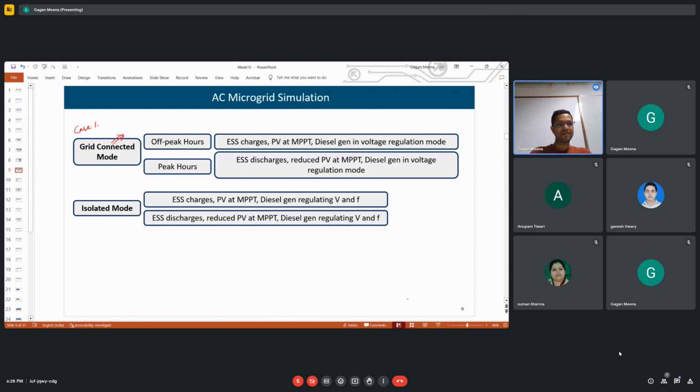So it will become L11, which is a self-inductance, into I1, plus the mutual inductance, M12, into I2. So it is because of the interaction. One is the self-term and one is because of that interaction.